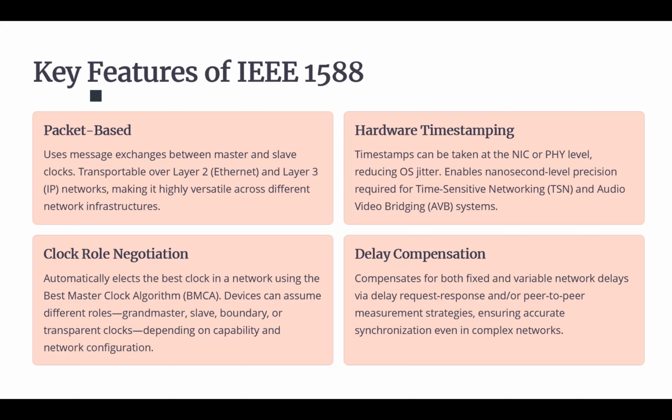So it's not just an offset delay. Sometimes we have error in the frequency when we have several devices, each of them with its own clock. We cannot guarantee that all the clocks would work at the same frequency and the same ticking speed.